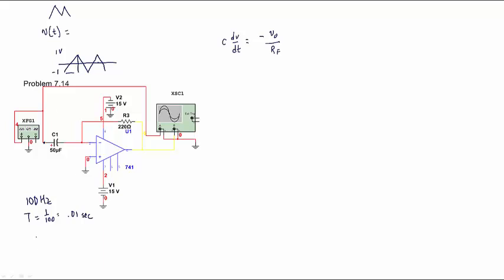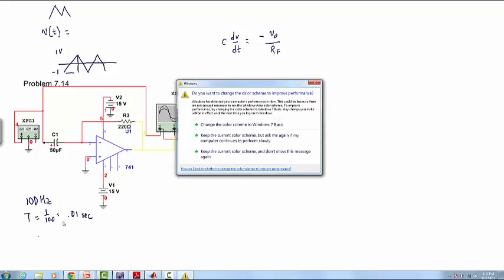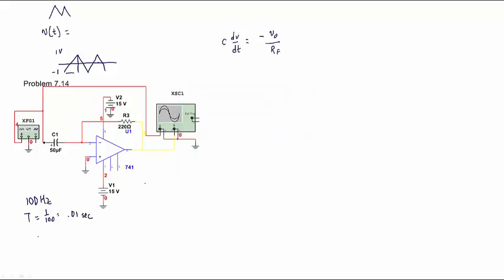I'm going to go from the change in the y direction, which is going to be 2, over the time that it takes, 0.01, so that would be 200. And then the other half of the period, when I'm in the negative side, my slope would be minus 200. So I could say it's 200 ramp of t, for example, in our notation.